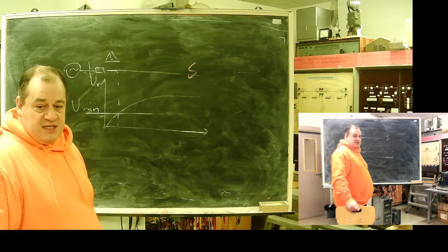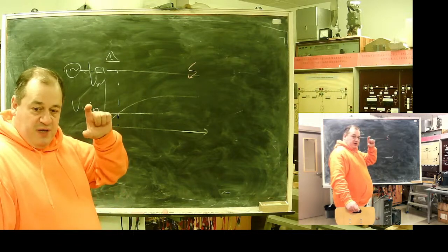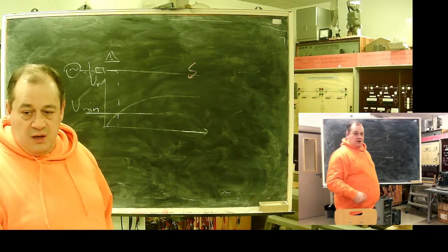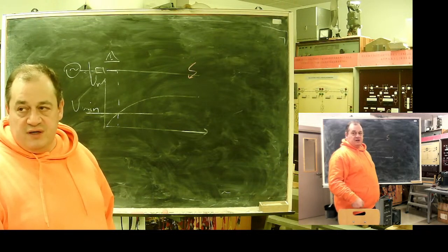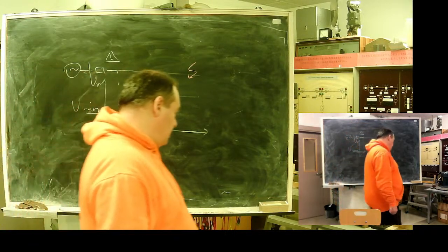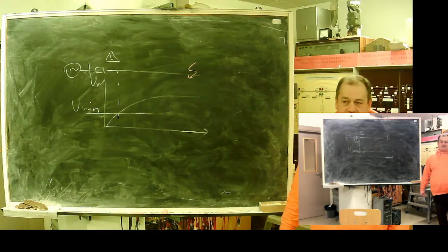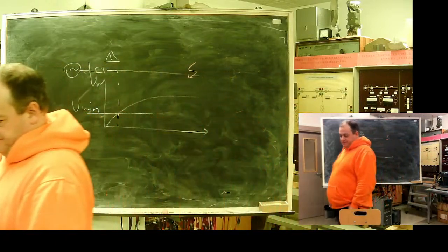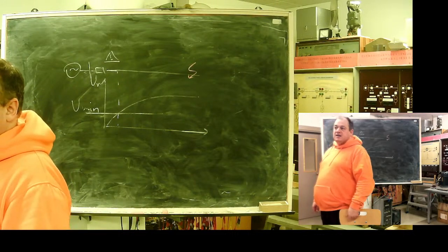In case there is not enough voltage, for example AB voltage is too low, the relay uses a signal from this resonance current powered from C phase. The distance relay in such a regime degrades to directed overcurrent protection. Modern relays do keep the value of voltage before fault, and it can be used